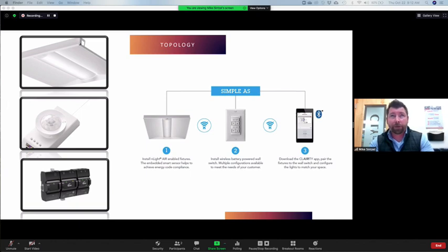Component-wise, you have a light fixture. That fixture has a driver inside and typically takes 120 to 277 volts AC. You have an integrated sensor, the one there center left. It's usually called a node. That can most likely be found at one end of the fixture or in the center, depending on fixture design aesthetics and what people want to see.